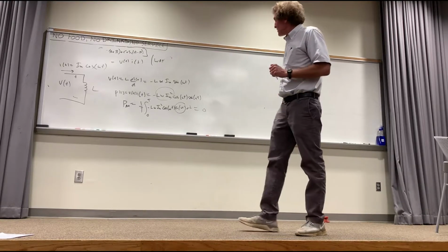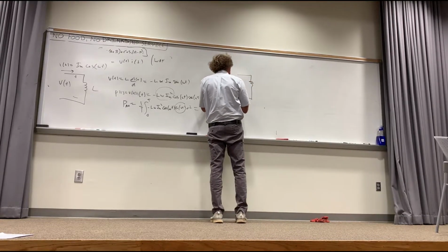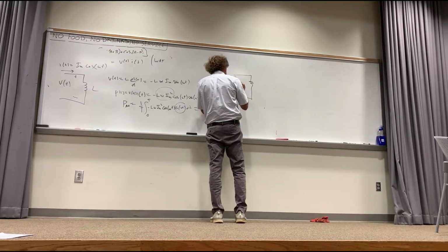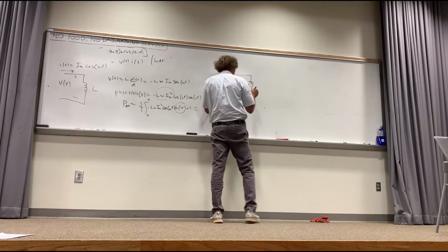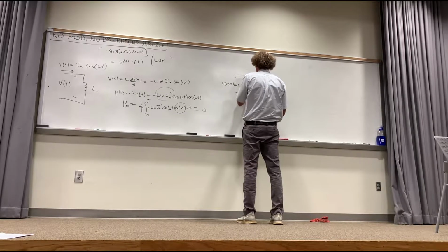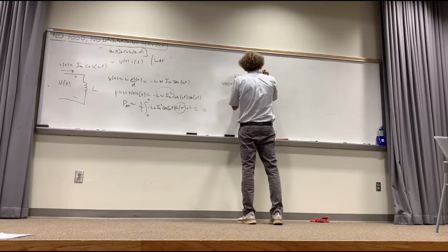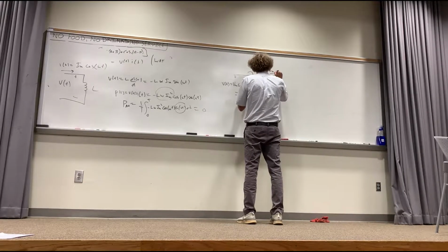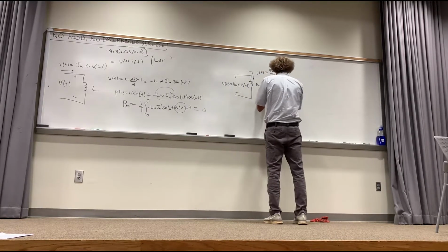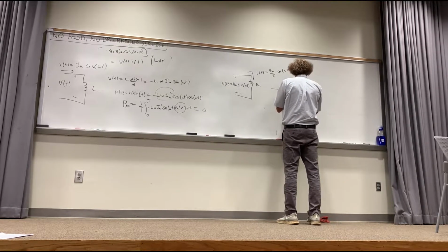As a matter of fact, I want to do one thing with the resistor to make sure we're clear on that. When we have a resistor here, and we're driving a voltage across it, v(t) is equal to Vm cosine of omega t. So it's a time-varying voltage that's periodic. It's got a frequency omega, and it's got a value R. I can say it's got a current i(t) equal to Vm over R times cosine of omega t.